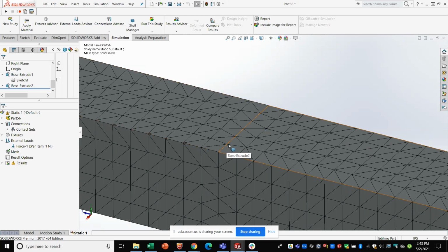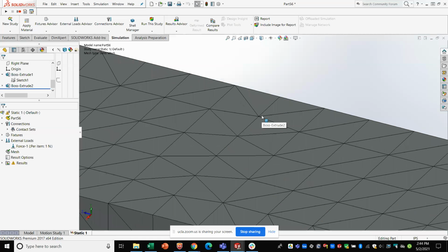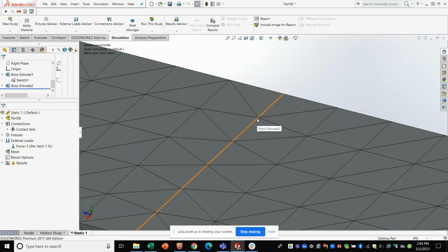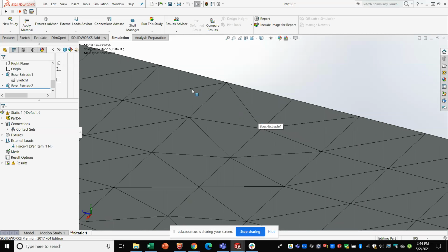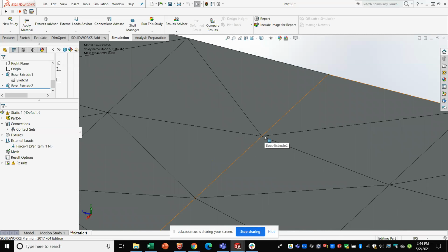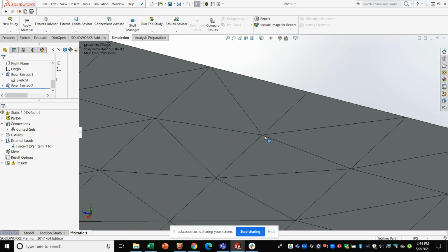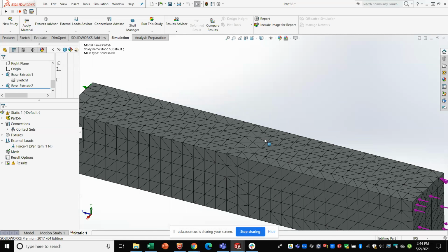It's forming all of their elements as part of matching nodes. So, for example, this node here is shared by both the left and the right parts. It's not two overlapping nodes that just have an infinitely short spring between them. It's literally the same node. And this is even more computationally efficient.